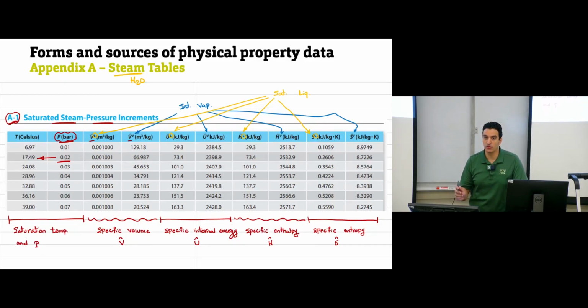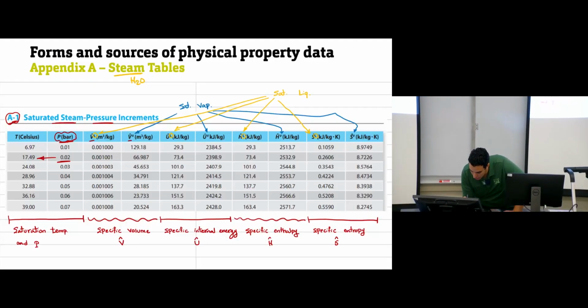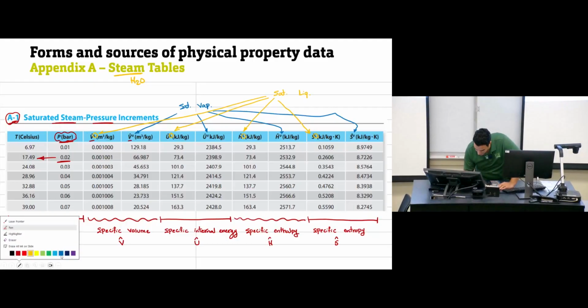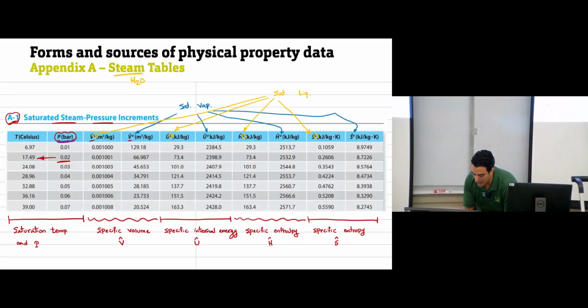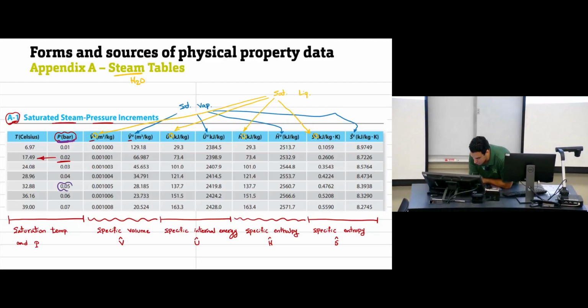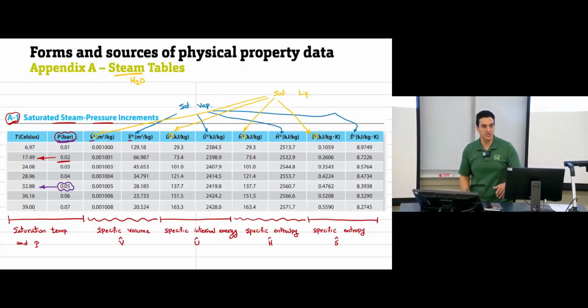Saturated liquid, 0.05 bar. Yes. So again, go to the pressure. Start at this one. This is the pressure column. Pressure is given, so I will use A1. Look at 0.05 bar. This is 0.05 bar. So the saturation temperature at this one is 32.88 degrees Celsius.